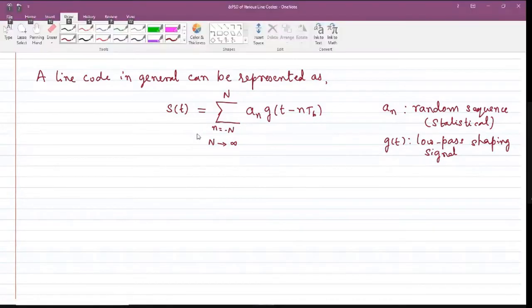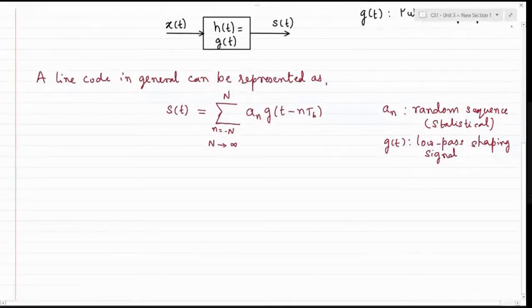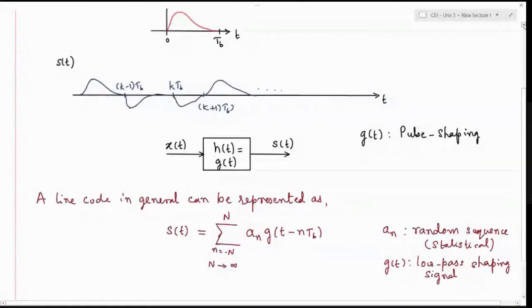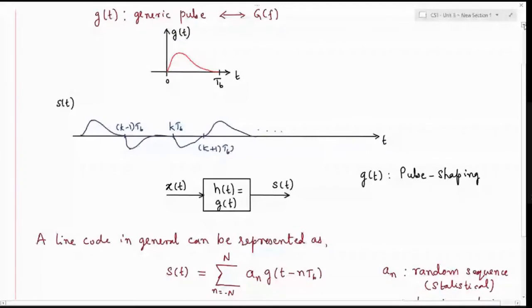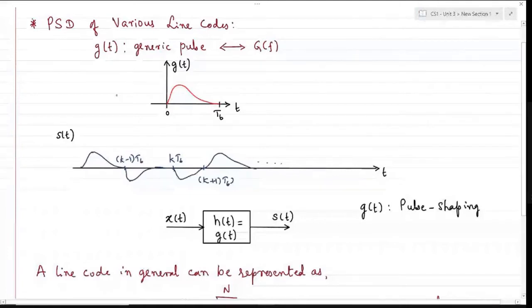So what exactly is the g of t, sir, the function? Yeah, g of t is this signal I have plotted here. g of t is simply a signal. I can say this is kind of an impulse response of a filter. Whatever signal is fed to this has to get convolved with this response to produce the output.